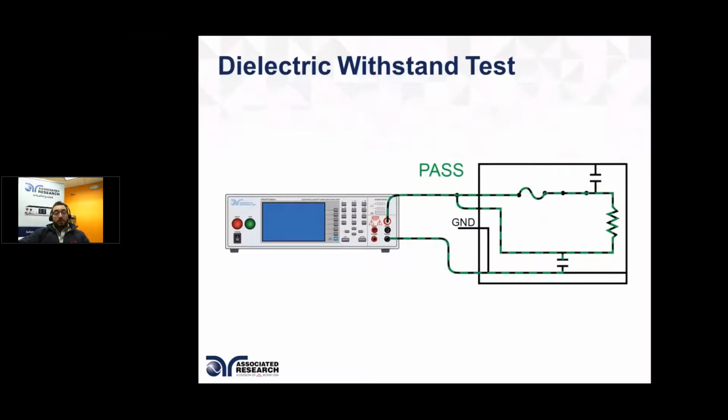So here's an image of the circuit of the high-pot test. On the top, if you can follow me here a little, you see the high voltage output is the little white connector, which is connected to the line and neutral of the device, which are the two current carrying conductors, and the return circuit is tied to the ground or the chassis. High voltage is applied between these two, between the hot neutral and ground, and a leakage current determination is made.